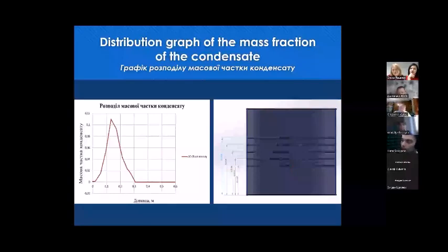So in the aqua distiller, we don't need like 200. Sorry, on the slide. You see the mouse? Yes. Okay. As we see about the efficiency of this drop catcher, it was high efficiency at 300 millimeters. So we can use only 3 partitions, which is 100 millimeters less length. So we can make a better construction, I think. In the aqua distiller, we have a drop catcher with 210 millimeter length, and my model shows that high efficiency can be reached with only 110 millimeters. Thank you for your reply.